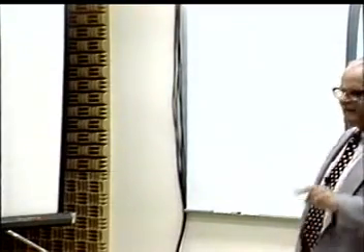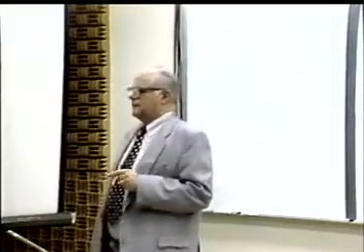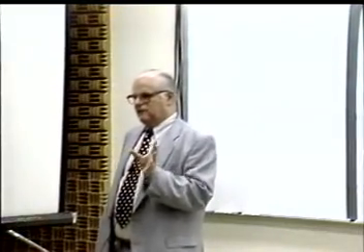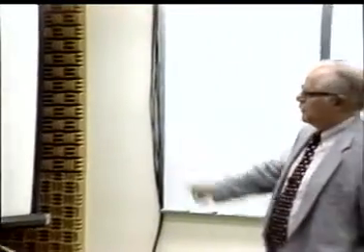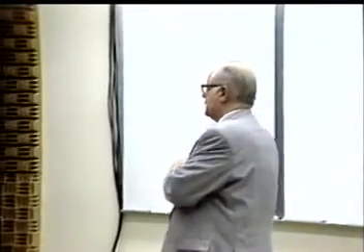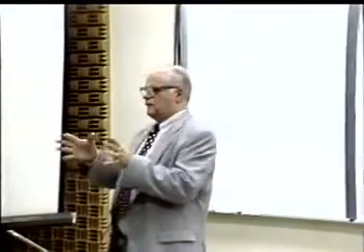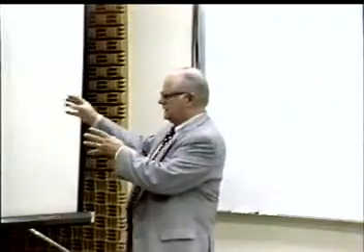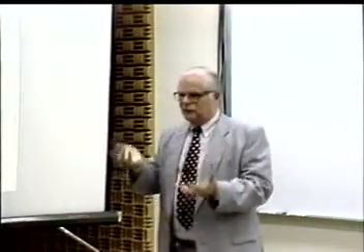Now, Koth's shell was presented in a report by Koth where he studied the B factor, he applied the B factor to anisotropic shells. He used membrane pre-buckling, contrary to here where I'm using rigorous pre-buckling. So essentially you could say that his results were level 1, and these results that I presented, in terminology of this deck, are level 2.